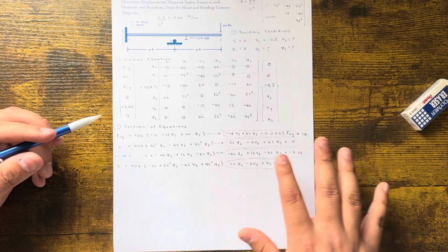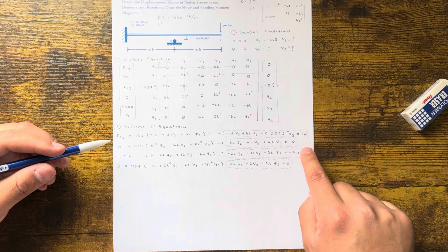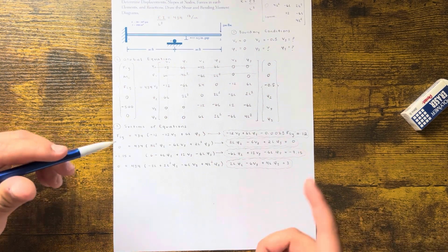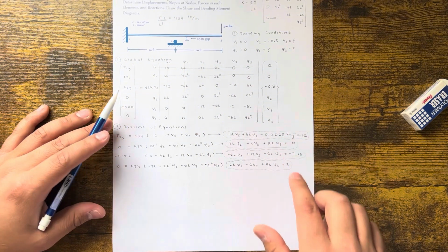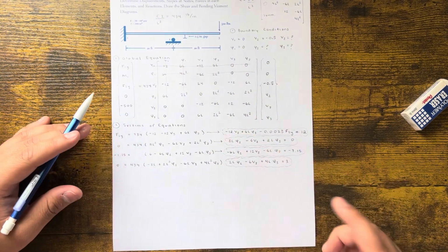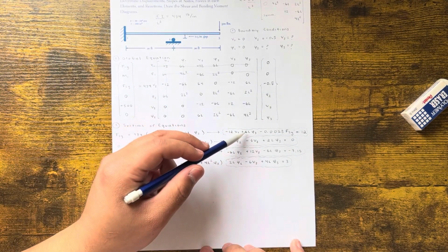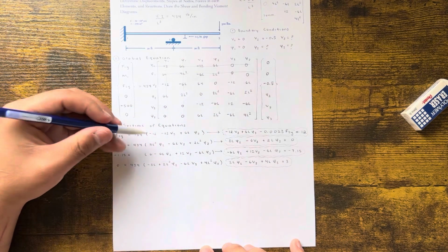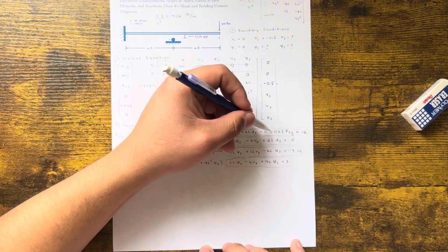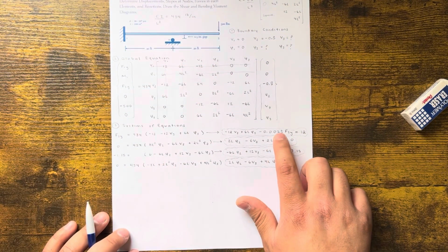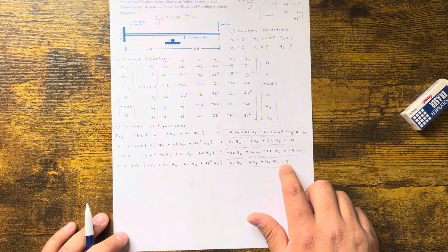So what you can do, after you do the organization, is move all the constants to the side. In this case, 12, 0, negative 7.15, and 3. And move all your variables to the side: Phi2, V3, Phi3, and F2Y. You don't see it here, but technically this is a 4x4, right? It's a V3, negative 12 V3 plus 6L Phi3. It's probably plus 0 Phi2, right? There's a 0 Phi2 somewhere. And then minus this number, 0.0023 F2Y. And there's a 0 F2Y here, 0 F2Y here, 0 F2Y here.